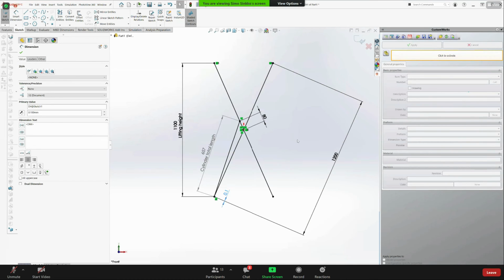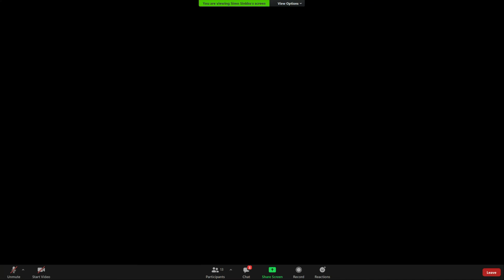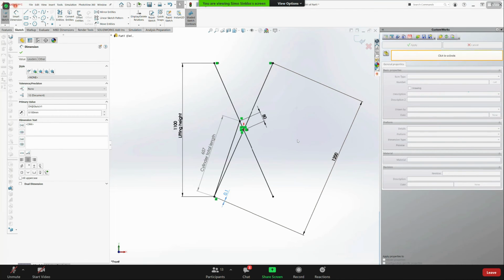And in a report, I would like to see this kind of sketch about the cylinder length in both positions, in fully down and fully up, and then the calculations, the free body diagram and the calculations, static calculations, that how much force you really need. And like I told, I suggest that you would use, for example, MATHCAD to create those calculations so that you are able to easily change the starting values.